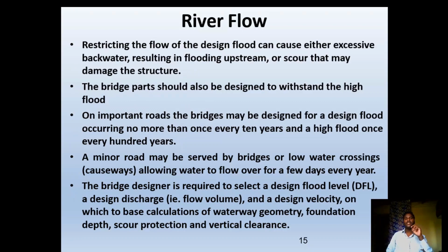Restricting the flow of design flood can cause either excessive backwater resulting in flooding upstream or a scour that may damage the structure. The bridge part should also be designed to withstand the high flood. On important roads, the bridge may be designed for a design flood occurring no more than once every 10 years and a high flood once every 100 years. This is an important one.